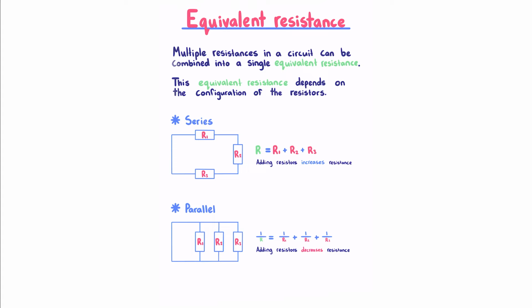And while the idea of adding another resistor seems like it should intuitively increase the resistance rather than decrease it, the most important thing isn't that we've added a resistor, it's that we've added an additional pathway for current to flow. And no matter how bad a pathway this is, because it will still allow more current to flow, the total resistance of the circuit must decrease.